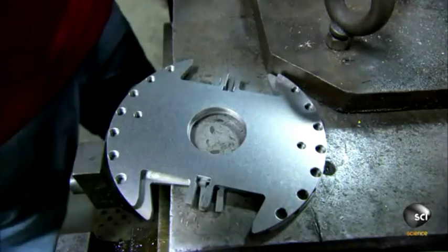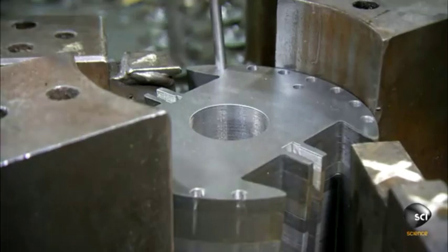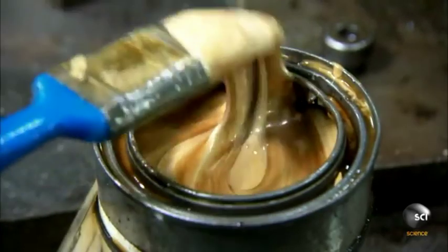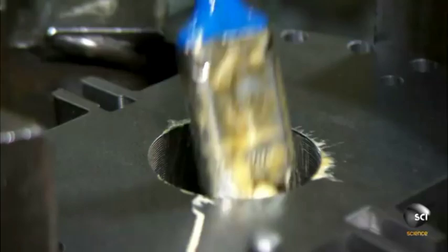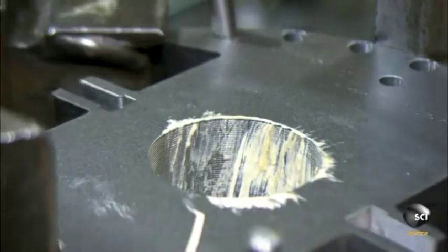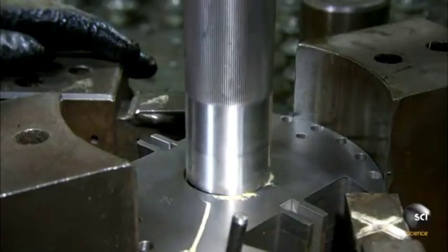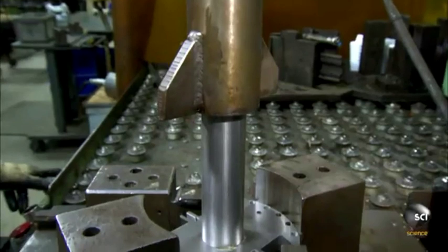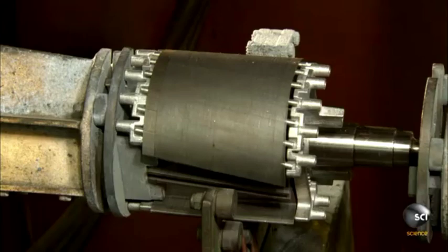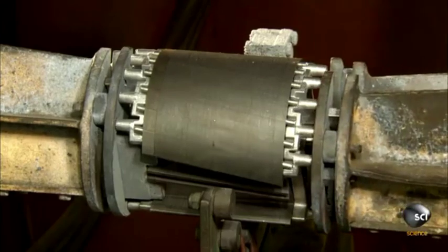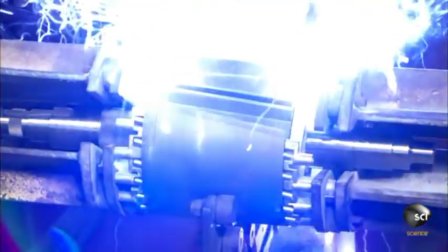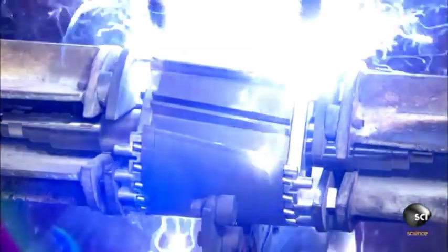To produce the alternator's rotating part, the rotor, the technician stacks laminated steel discs to the same height as the stator core. He lubricates the opening in the center of the discs. He inserts a shaft, and a press pushes it into the stack to complete the installation. Then it's over to an automated welder. The machine grips the rotor at both ends and slowly turns it, as a robot welds both caps to the rotor body.